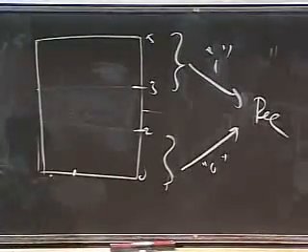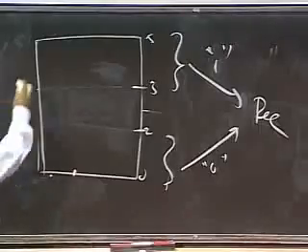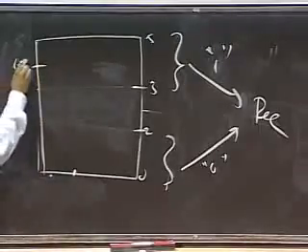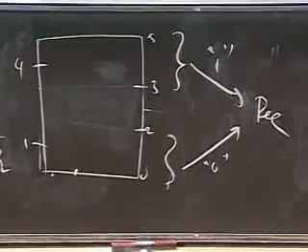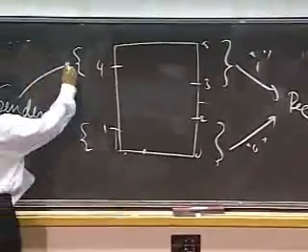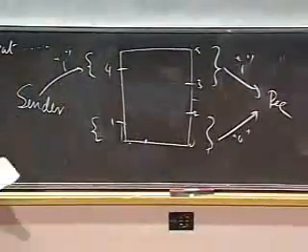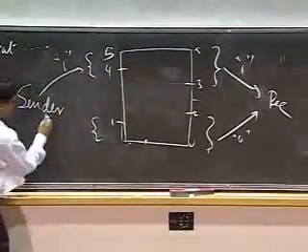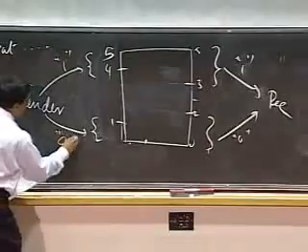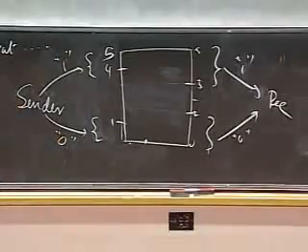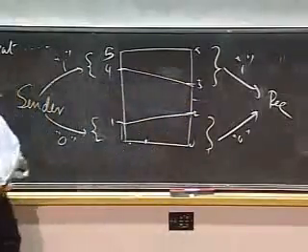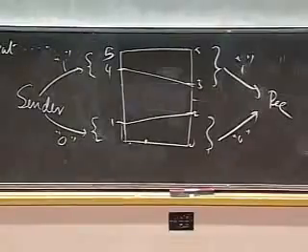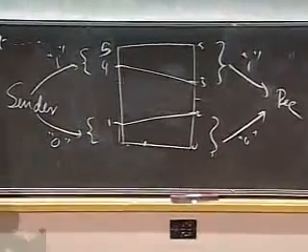So what I'm going to do is hold the sender to tougher standards, maybe 4 volts. That is, tell the sender that if you want to send a 0 or a 1, for a 1, you have to send a value between 4 and 5, and for a 0, a value between 0 and 1. So the sender is now held to tougher standards. So this is what my chart looks like. Now I do have some noise margin.